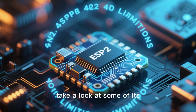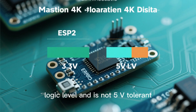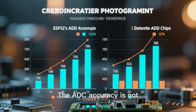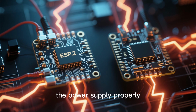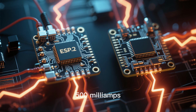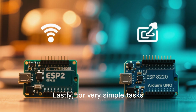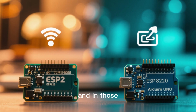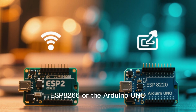Now let's take a look at some of its limitations. First, it needs a 3.3V logic level and is not 5V tolerant. The ADC accuracy is not as high as dedicated ADC chips. You need to design the power supply properly because the ESP32 can draw spikes of more than 500 milliamps during Wi-Fi transmitting. Lastly, for very simple tasks, you might find it overkill, and in those cases, you can use the ESP8266 or the Arduino Uno.